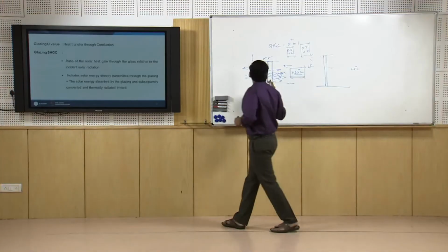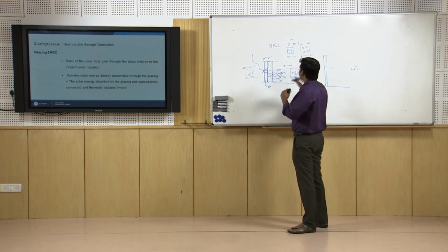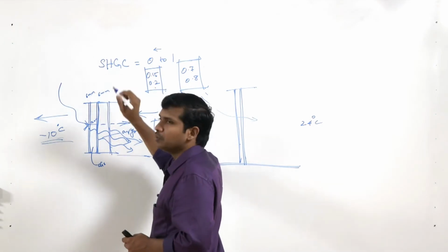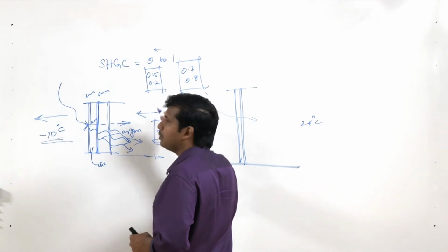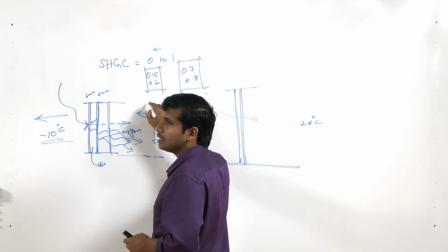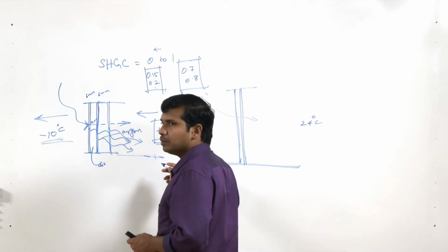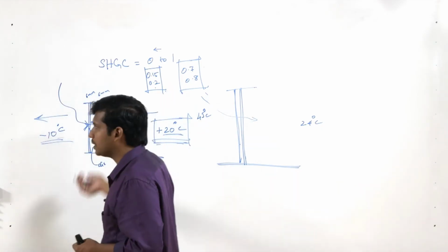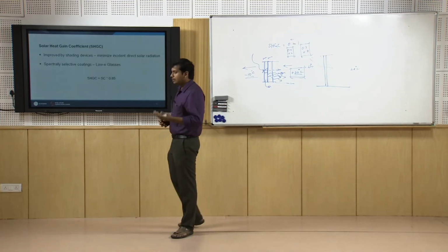There is a lot of difference if you take a particular Indian location, any location, most of it is warm or hot, except for the northern belts which are really cold. Solar heat gain coefficient has a higher impact compared to U value. Most of the tests and experiments we conducted, we found a higher impact. Say for example, when I reduce the solar heat gain coefficient from 0.8 to 0.2, there is a drastic reduction in the cooling energy, and the improvement in comfort is also much higher compared to the reduction in U value. U value is also crucial, but solar heat gain coefficient takes the front seat if you are designing for a hotter location.